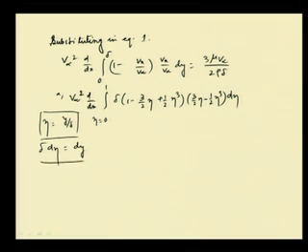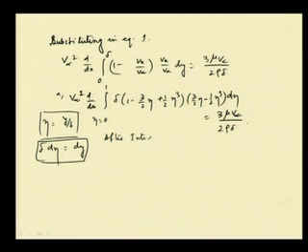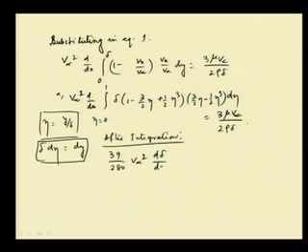So, dy is replaced by delta into d eta, and therefore the delta term comes into the picture over here, and this becomes equal to 3 mu V infinity by 2 rho into delta. Okay. Now, after integration and putting the limits 0 to 1, we get the expression 39 by 280 V infinity square d delta by dx equals mu into 3 mu V infinity by 2 rho into delta.